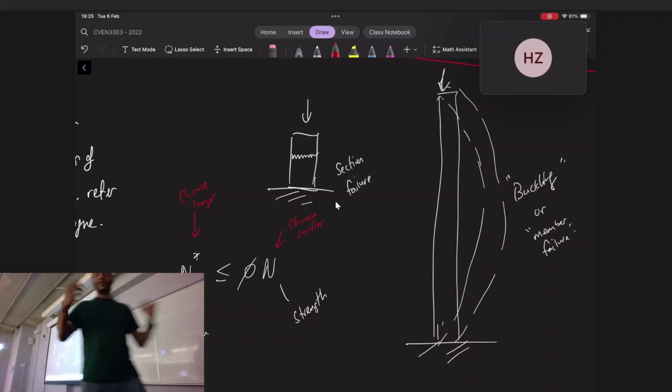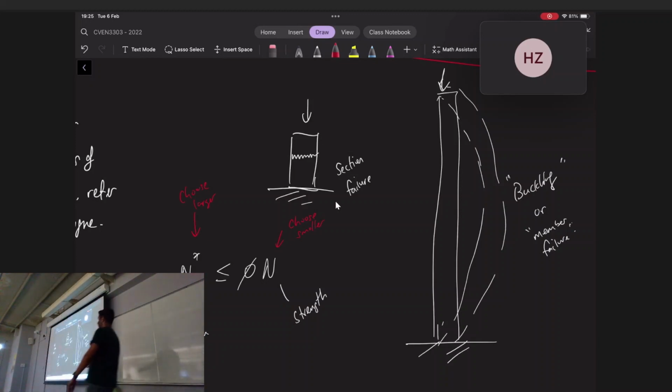So what you will end up doing is, right now this column here. By the way, that's the other thing you've got to know: terminology. Beams are always horizontal elements. Columns are always vertical elements, and that will never change. Strictly speaking, when we're talking about columns, we're talking about the vertical elements, pillars. Beams, joists, whatever, those are all horizontal elements. Now, to answer your question, this one is restrained on two ends: on the bottom and in the top. So there's only two restraints.